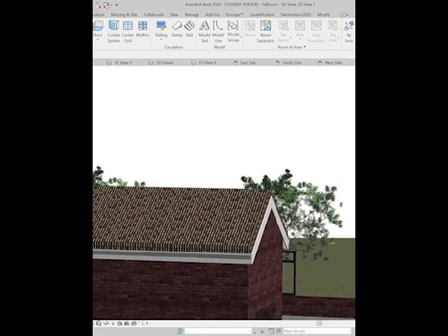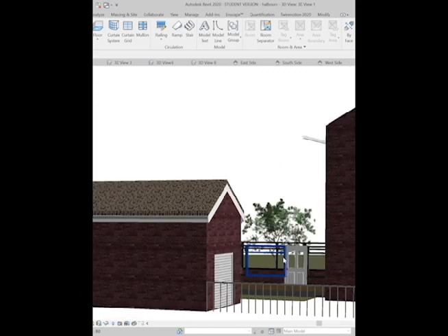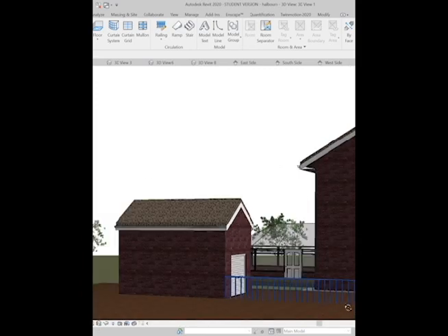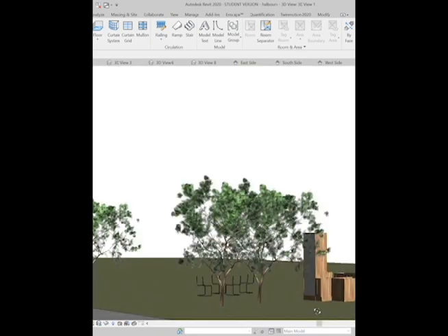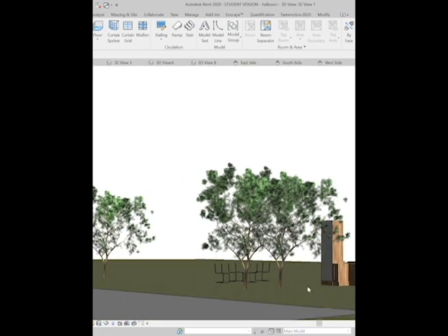What else can I immediately see? I think there's a lot wrong with it. The topography surface again has not been done correctly. It should have been done as a split surface rather than a build.